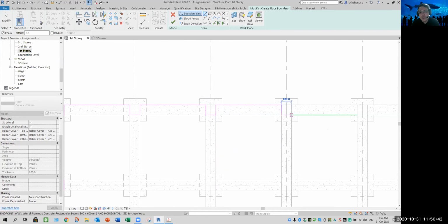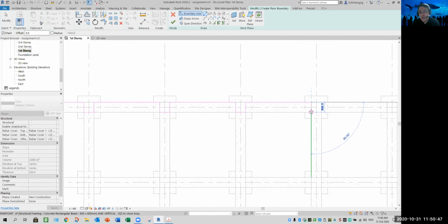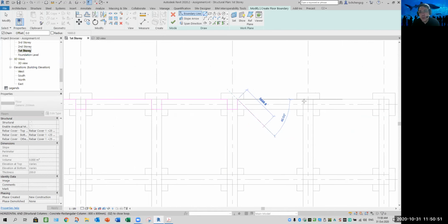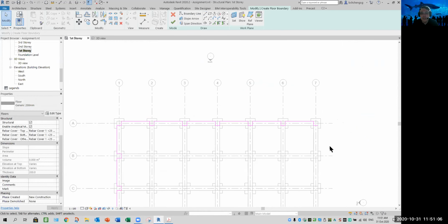Now in a structural slab, column or beam, when you cut an opening, if all these lines, called shape handles, that I'm doing now, overlap, it'll give you some error. So you guys got to be extra careful on that. Okay, now I'll do something like this.